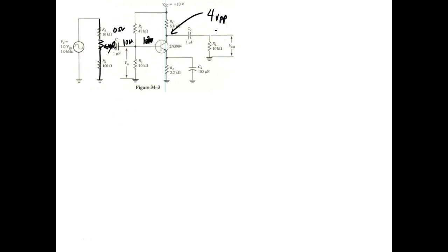So instead of trying to deal with millivolts on the left-hand side, I'm going to deal with volts on the right-hand side. So I'm going to start adjusting this pot wired as a rheostat, going up until this drops down to 1/2. So it's going to drop down to what? 2 volts. As soon as I do that, I know that the value of that equals the value of that.